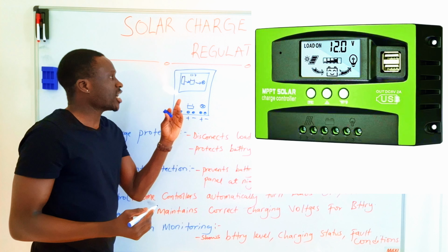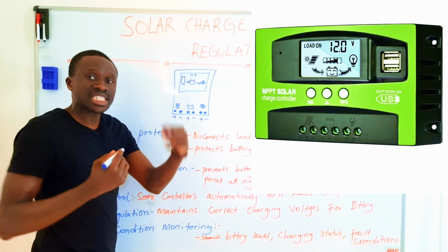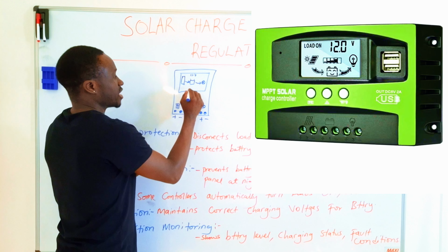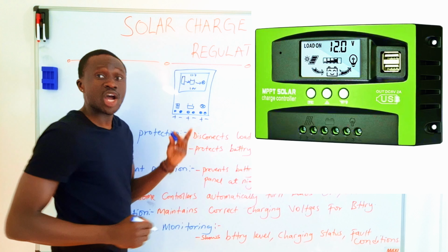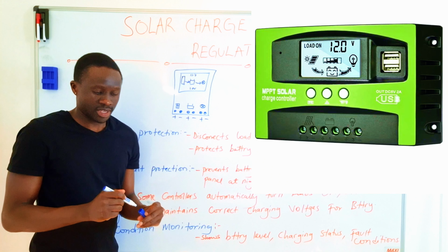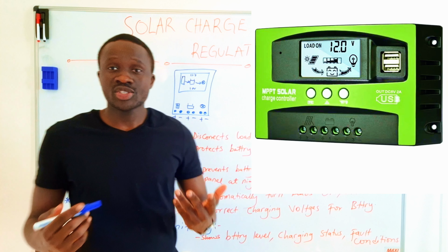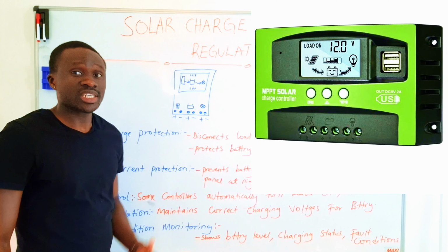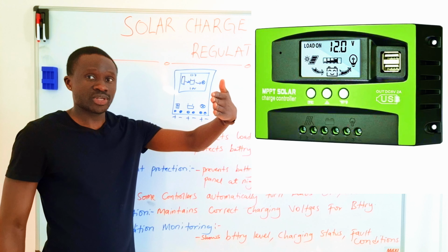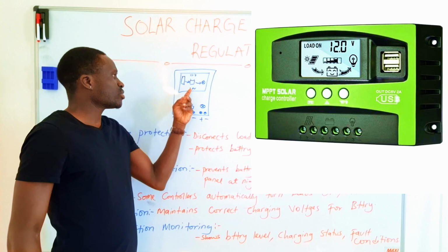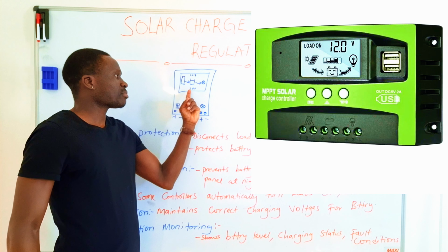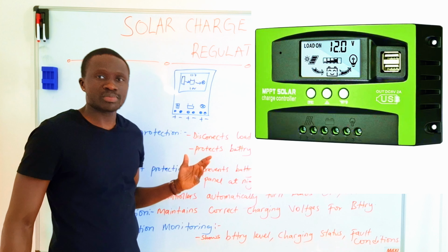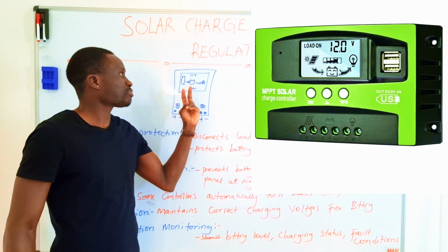Okay, now when the battery is low, it will show you that the battery is at 10 volts, a low battery. And even if you're a customer or a technician, that's why I told you, just come and first read what the charge controller is telling you. Where is the fault? It will show you that it is night, but the battery is 10 volts. Even though you don't measure, it has measured for you.